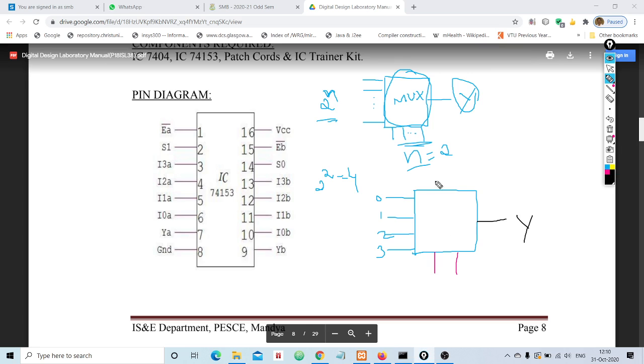So we call this a multiplexer. More specifically, this multiplexer is called a 4:1 multiplexer, or 4:1 MUX. Make it simple. What does this 4 stand for? This 4 represents the number of inputs and this 1 represents the number of outputs. In case of a 4:1 multiplexer, how many special input lines will be there? 2, correct? So this is how, or in this pattern, multiplexers will be available in the market.